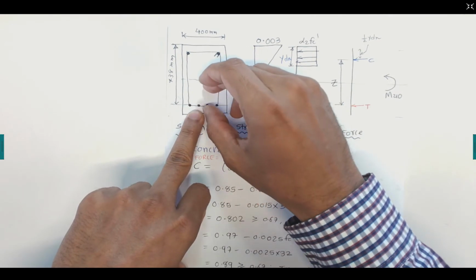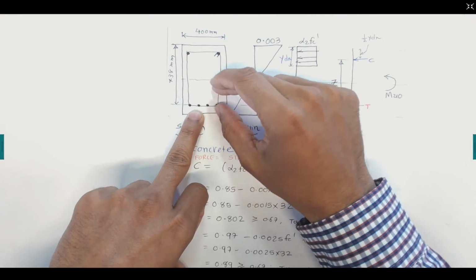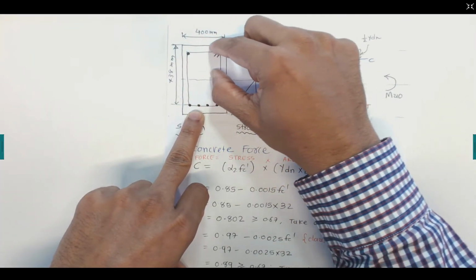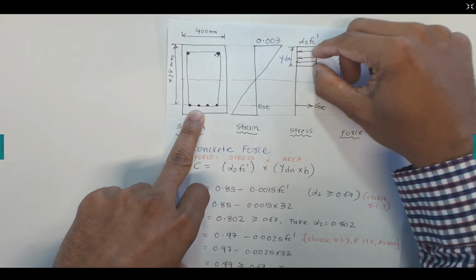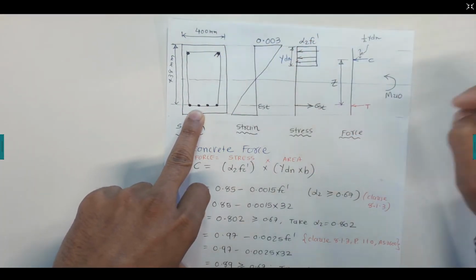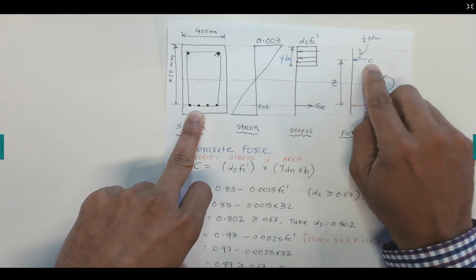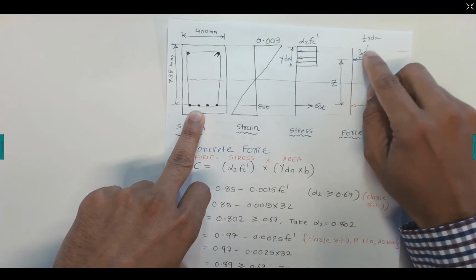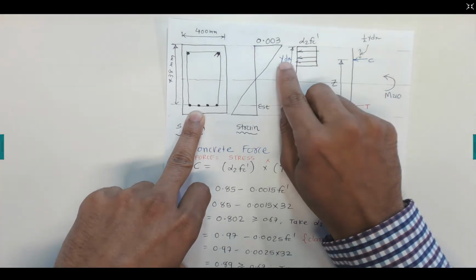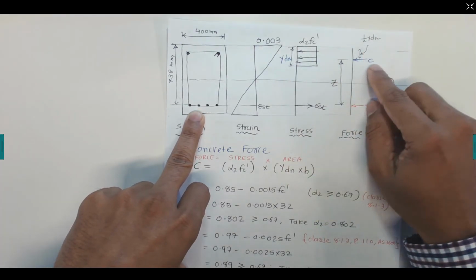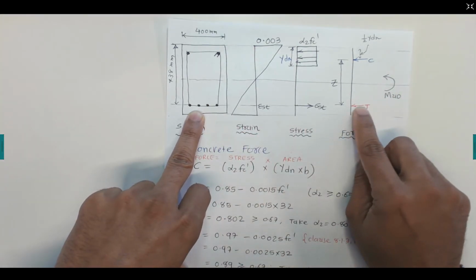Concrete below the neutral axis is subjected to tension, so there are no forces in this region. There are compression forces, not taking the whole portion but just taking the average of these effective stresses here. Now if I take this whole distribution as one force, that is the compression force in the concrete, it should be applied at the center of this length, which is half of gamma dn. And similarly we have the tensile force in the steel bars, which is applied here.